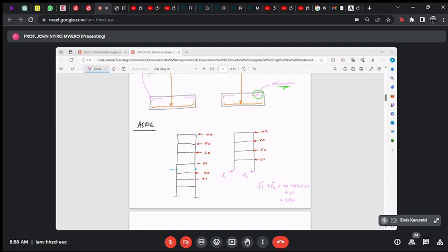All right. Thank you. But in actual fact, as you go down, the shear that needs to be resisted by every level increases. So if you're checking the total amount of shear, the total shear at any level is all the lateral load applied above that. So it goes on increasing. It's cumulative as you go down. So that when you get to the foundation, the cumulative is actually the base shear.